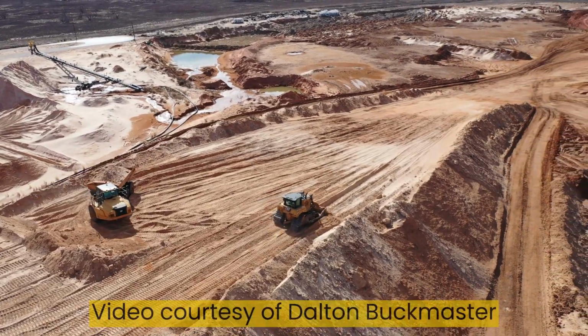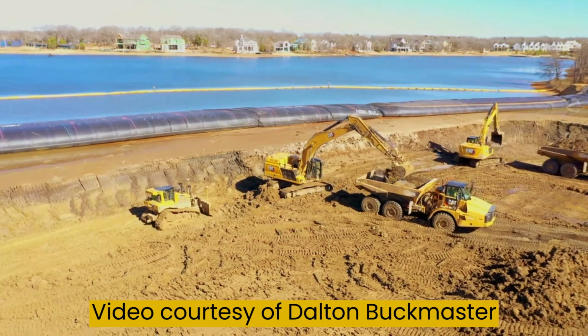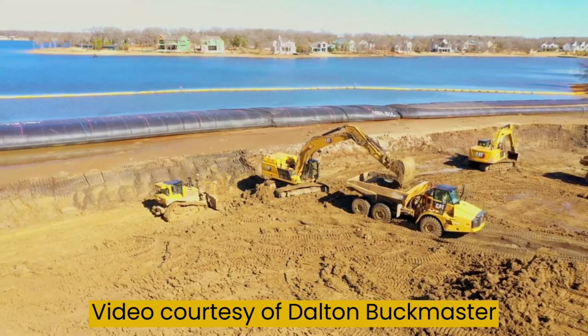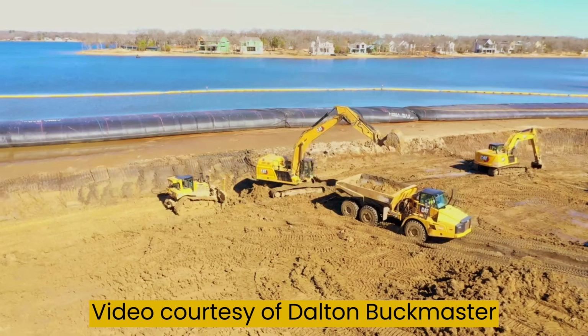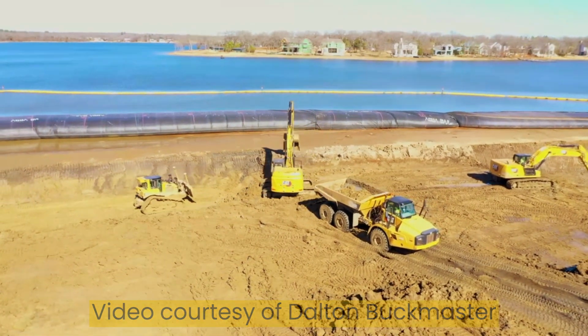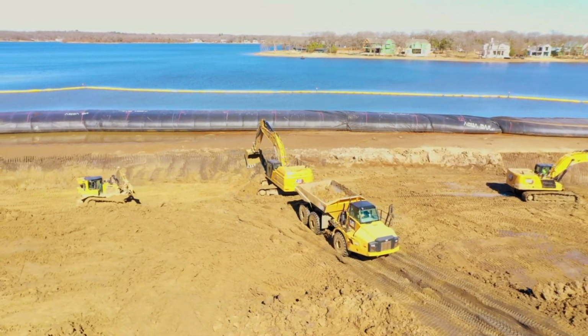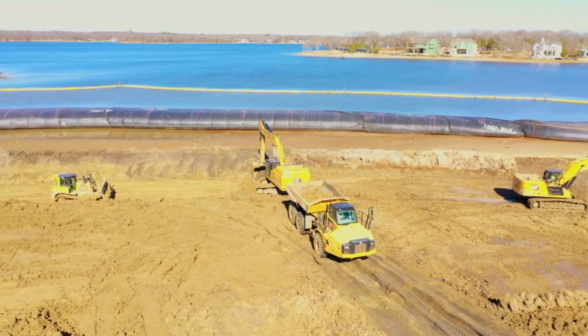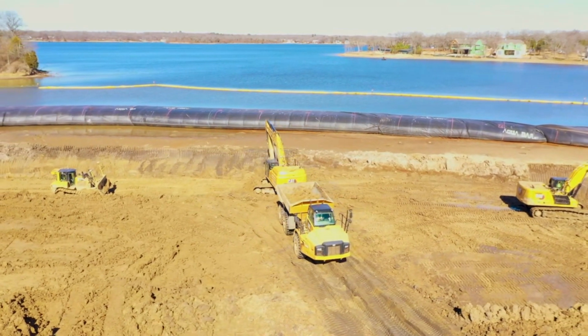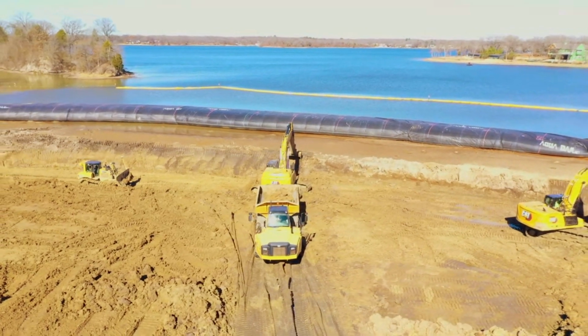Operating near water. When working near water is necessary, life jackets or personal flotation devices, PFDs, are required in the machine. PFDs will be worn by persons performing work where there is a danger of falling in the water. This is any time within 10 feet of water's edge. The water level, in a body of water, or elevation should be maintained as low as practicable.